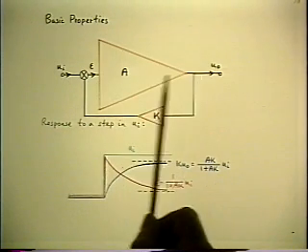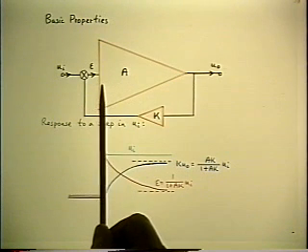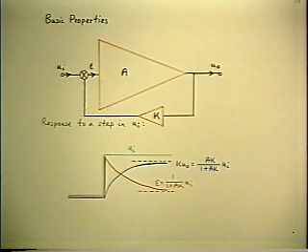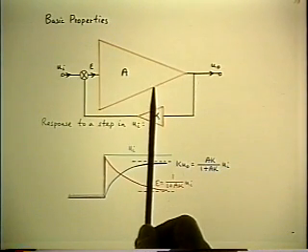The forward path has a huge gain of 100 dB, which is 10 to the fifth. Multiply 10 to the fifth by 1.5 volts, and you do not get 150,000 volts coming out. Because what happens is something hits the stops.